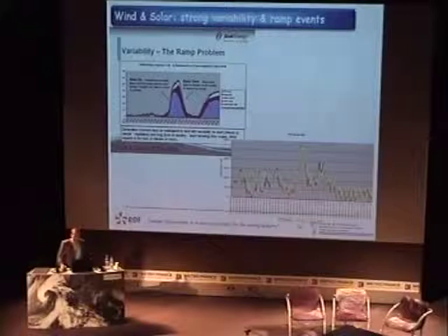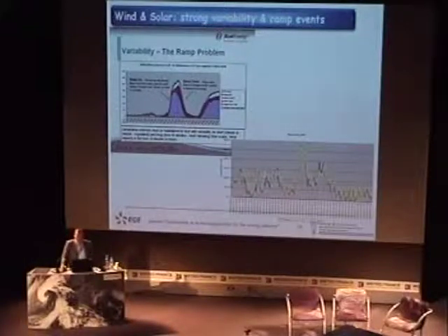Well, of course, with the introduction of massive wind and solar production in all energy systems, we are depending a lot on wind and solar production, so wind and solar radiation. One particular problem is linked to the ramping. What we call a ramp is a strong variation in amplitude in a very short period of time, either up or down, because in all the countries where the integration of renewable energies is a basic rule of the system, you of course have to decrease or increase the production of the other production means, and most of them are not as flexible as hydro, for instance. So it really poses a problem to the network managers.